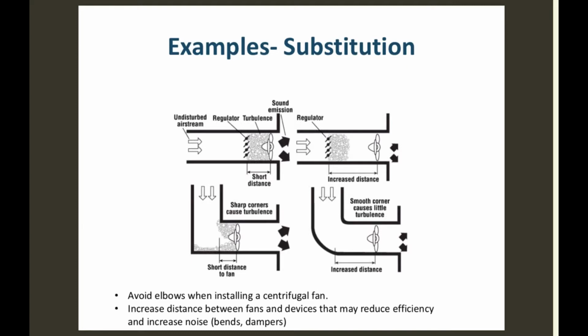This one over here, it seems like a couple of those are not working, right? Or they're blocked or are turned off. And these two up front here are taking all of that air that would go through these ones in the back, and they're blowing it in here very fast, perhaps a lot faster than it's necessary. And back there's dampers that they can use to control the flow of air that's going through this ductwork, right?